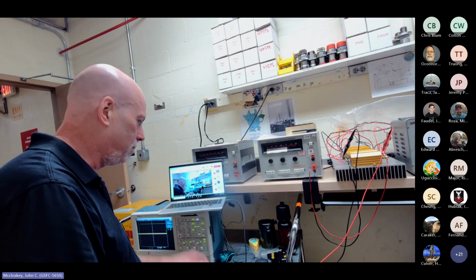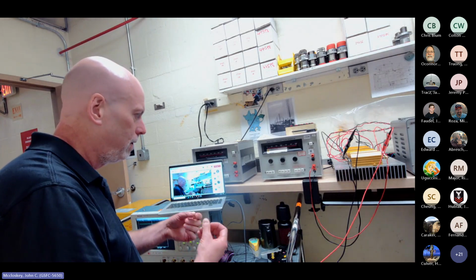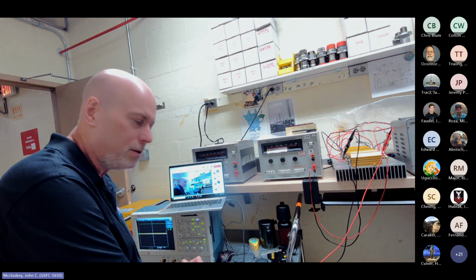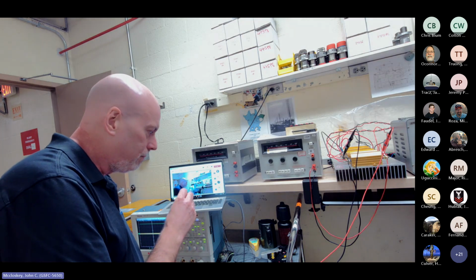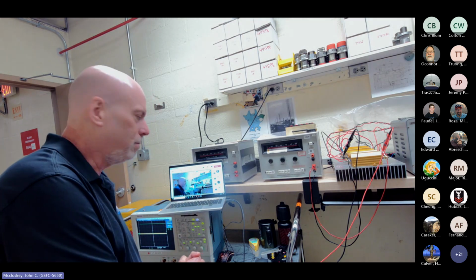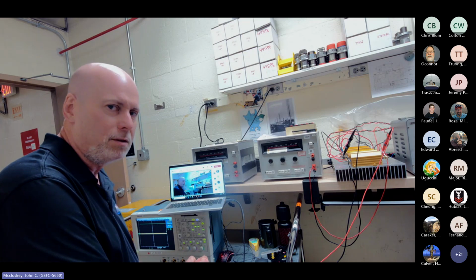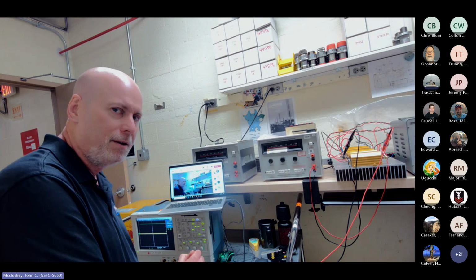This is all just the pre-calibration setup, but I say this for all conducted or any kind of susceptibility injection test: don't understate the importance of the pre-calibration step. It is extremely important. That's where you're characterizing what it is you're injecting.